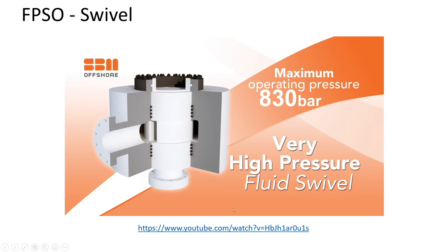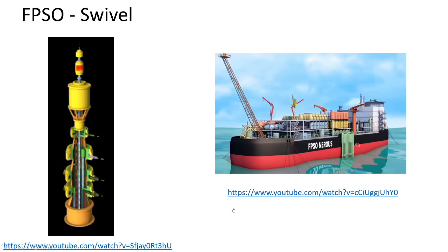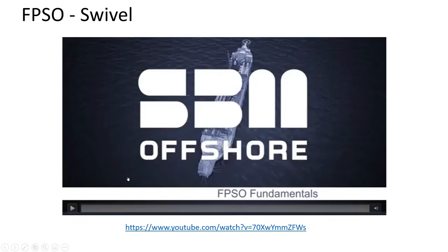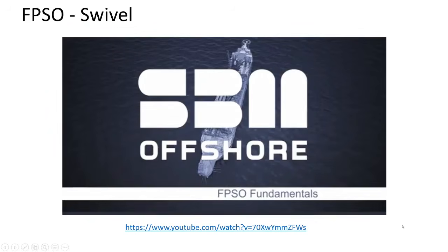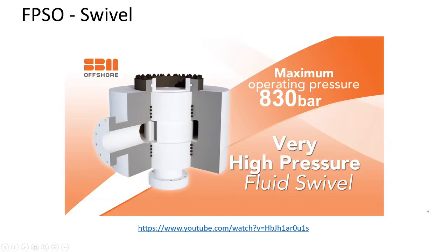One comment I have is that, because of the dimensions, you have to design the swivel very specifically for the fluids it is going to carry. If you need more volume, it will be bigger, and the seals and everything need to be more careful and are very costly. So many times there are constraints on how much fluid I can produce or inject just due to the swivel, because it is a critical component, and making it bigger is challenging.